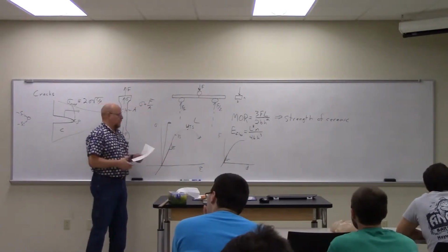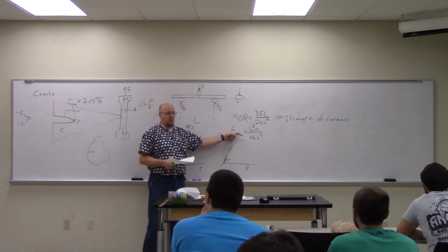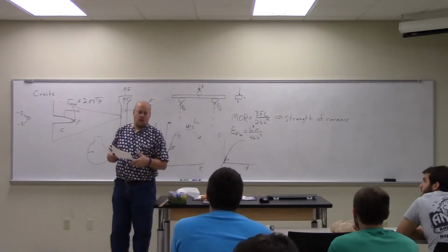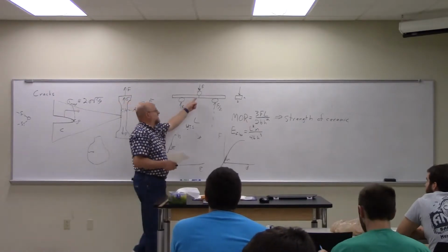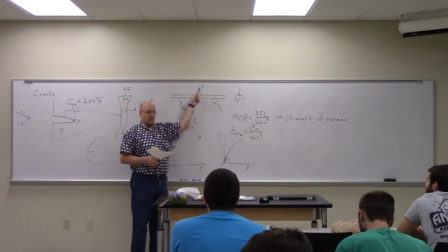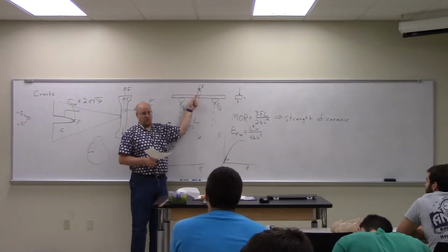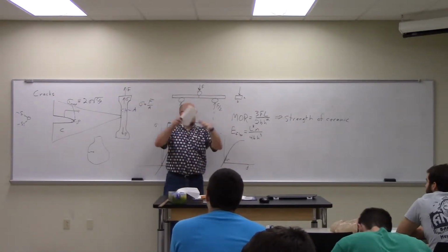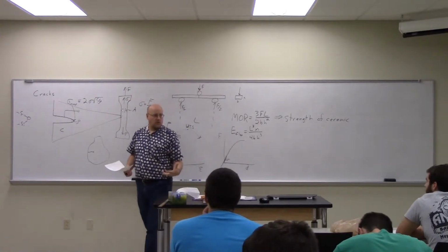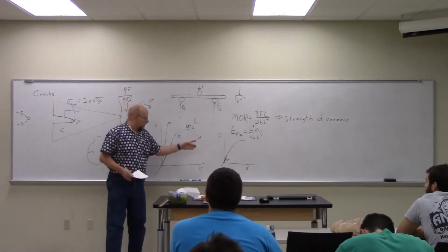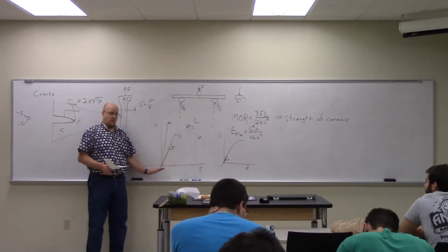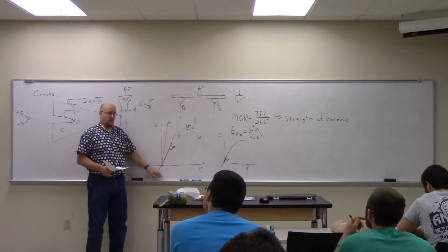Yeah. So the reason we're doing it is because the flexural test has both compression and tension happening at the same time. Compression on the top half and tension on the bottom half. So this measures the aggregate compression and tension behavior of the polymer, because it's different. The polymer isn't symmetric about the origin. A polymer has different behavior in tension than it has in compression.